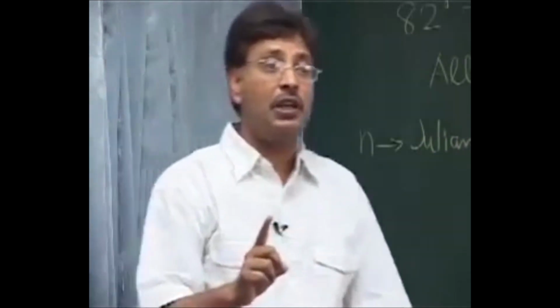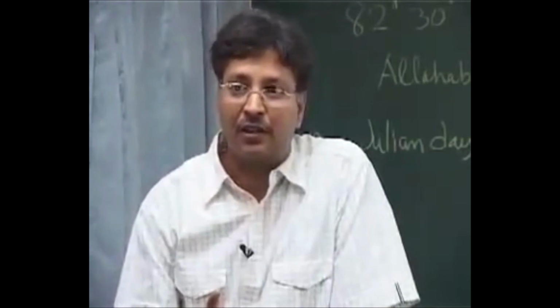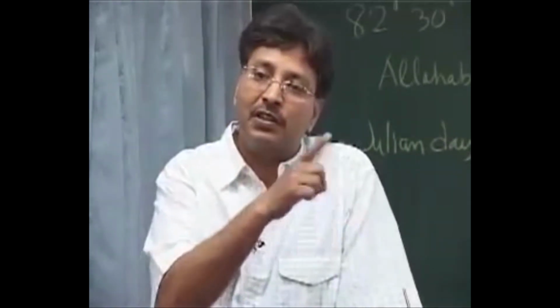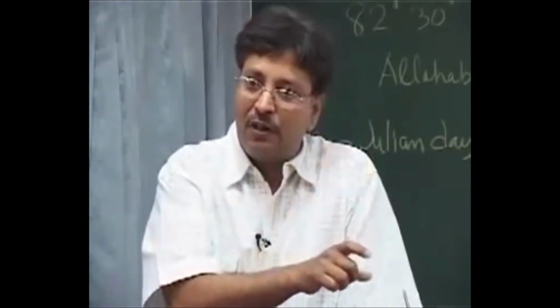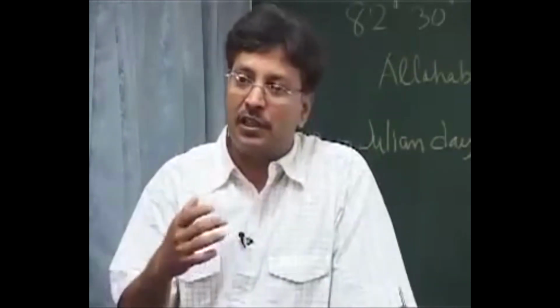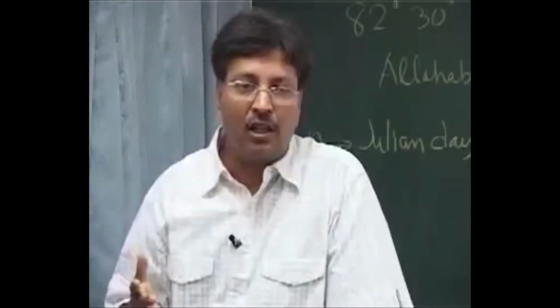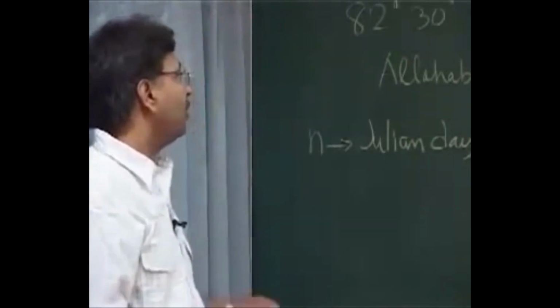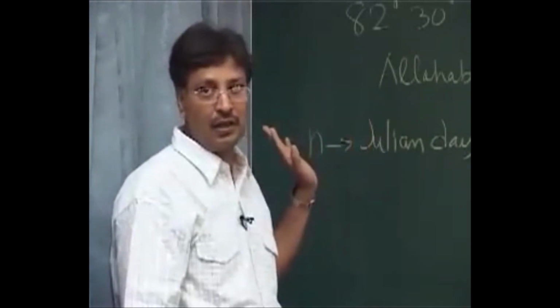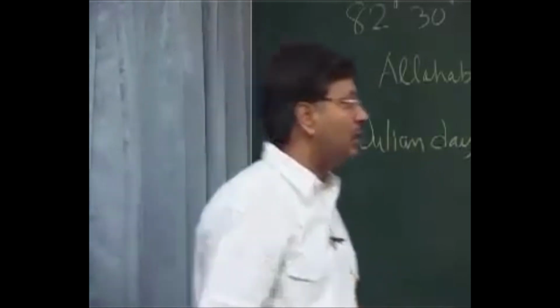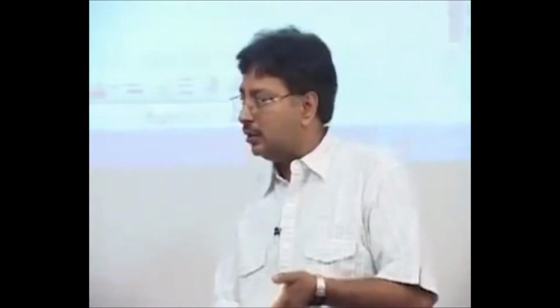The other thing you will need is the surface wind. Okay, this R you again compare with the first table which I gave you, with the surface wind which was 2 meters and this and that, 6 and things like that. So then I can really find out the stability class. I don't think I should have anything below this, but let's just scan. Okay, see the cloud cover, fine. Okay, this information is enough to calculate the stability class.